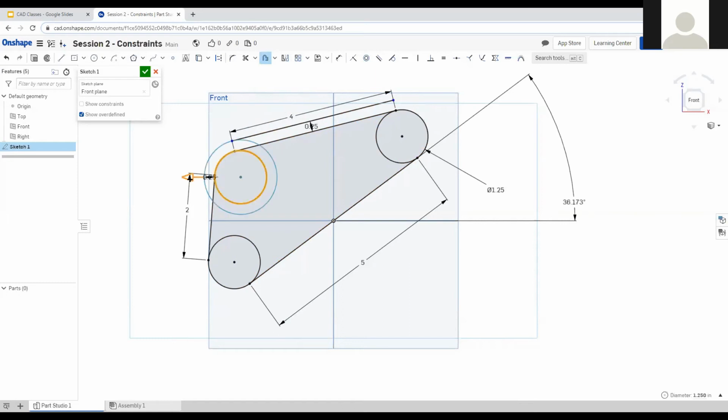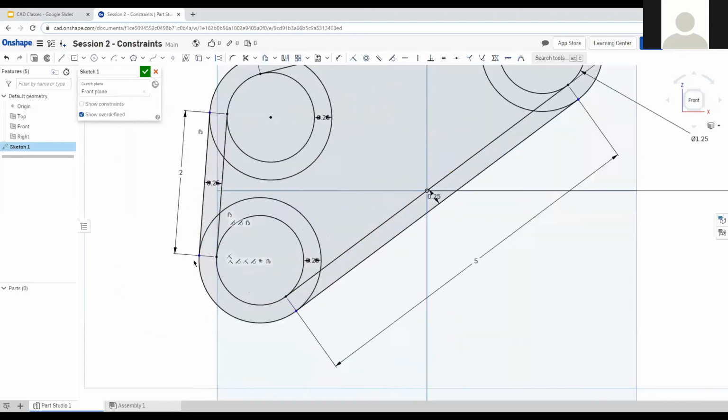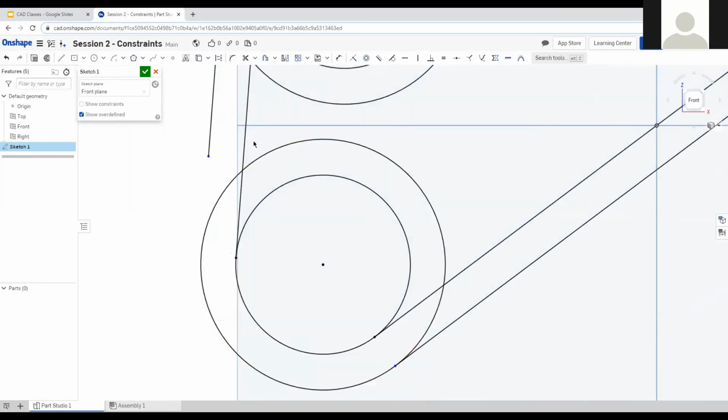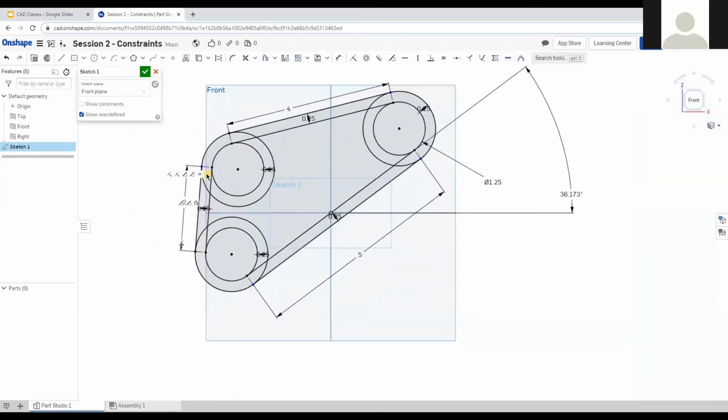And then we're gonna offset this. Let's do 1/4 inch too. Yeah, I like that. 1/4 inch here. 1/4 inch here. And you get the idea. Basically, as we keep doing this, we have this 1/4 inch boundary around the entire thing. I should probably set this to be constant to here, because that blue line there means you can drag it in and out, but no, this is supposed to be attached to the circle. Should not be any problems here. We're gonna go around doing that for all these.